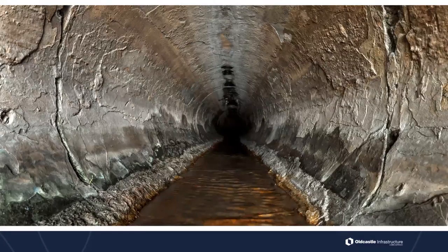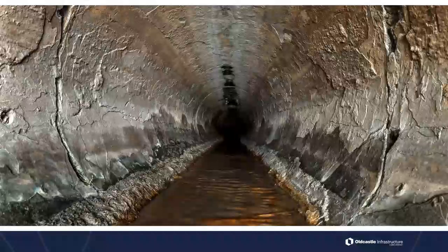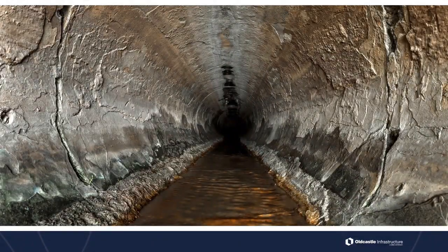Okay, so MIC, let's talk about microbial induced corrosion. There is a lot of misinformation about MIC, and I'm hoping we can clear up some of that misinformation today. The reality is that individual instances of MIC are heavily dependent on a lot of different factors, including but not limited to wastewater characteristics, activity of relevant microorganisms, the environmental conditions, waste stream hydrodynamics, the material properties of the concrete, the geometric characteristics, and even the intended function of the structure.